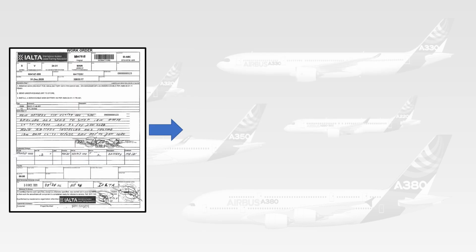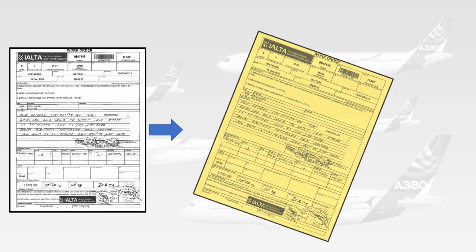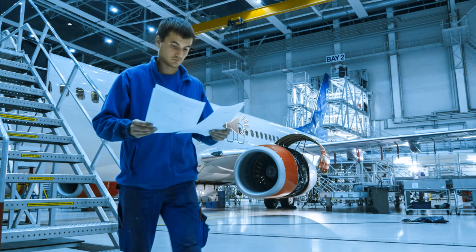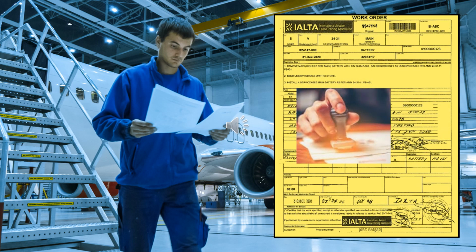When performing a routine task and we notice an issue or defect, then an NRC, non-routine card, is raised from the routine task card number so as to maintain continuity with the MPD task number. When the engineer has rectified the defect, they will state the action performed on the NRC and apply the certifier's DFP along with any associated references to the relevant OEM manuals.